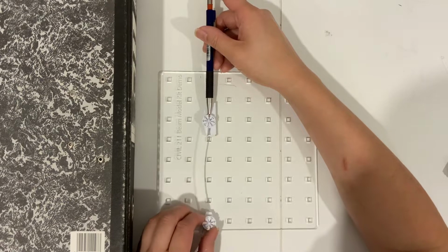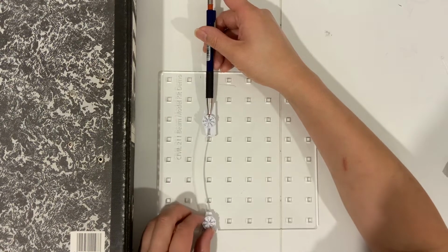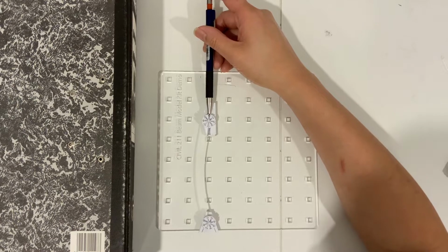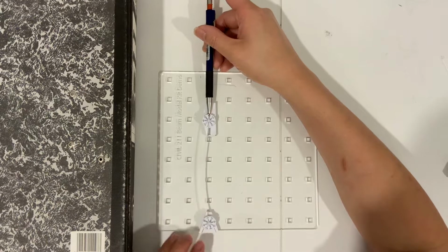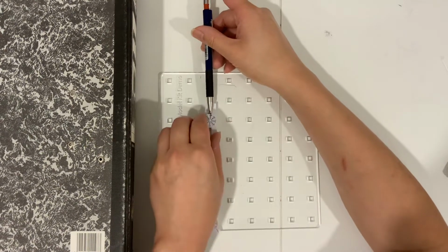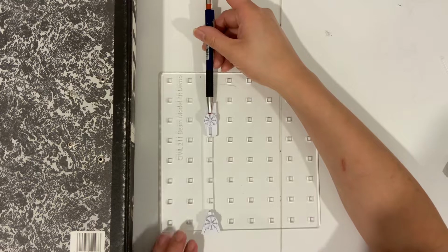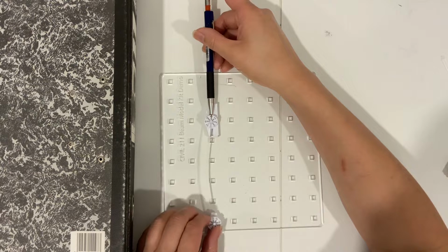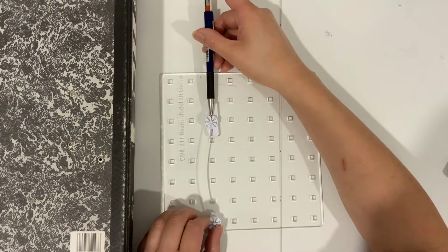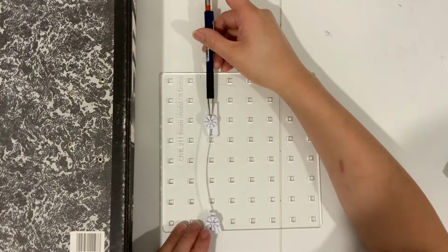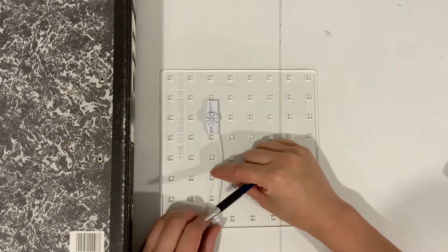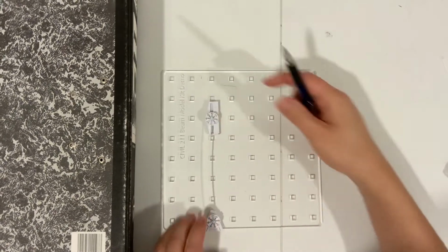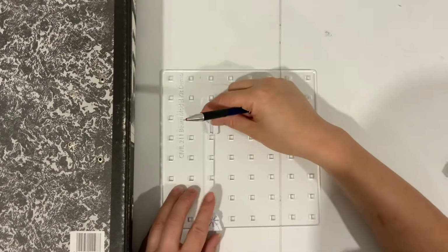Okay. So when I stick a load there, this is what's known as an instability, and the instability is called buckling. So I'm sticking an axial force down there, and suddenly it springs out. Yeah? So you can see it there, and that's called buckling. So before we go any further, it's not the same as bending. Bending is when you've got a lateral force coming in that direction there.